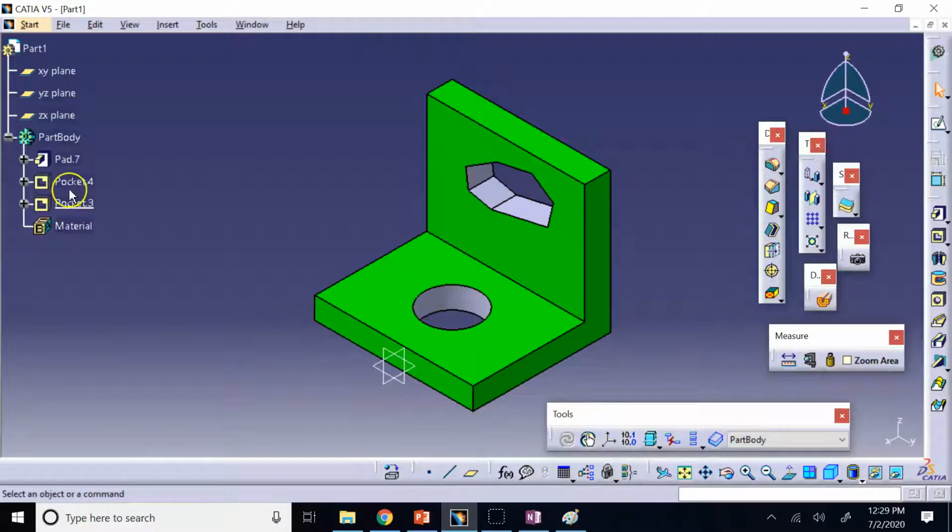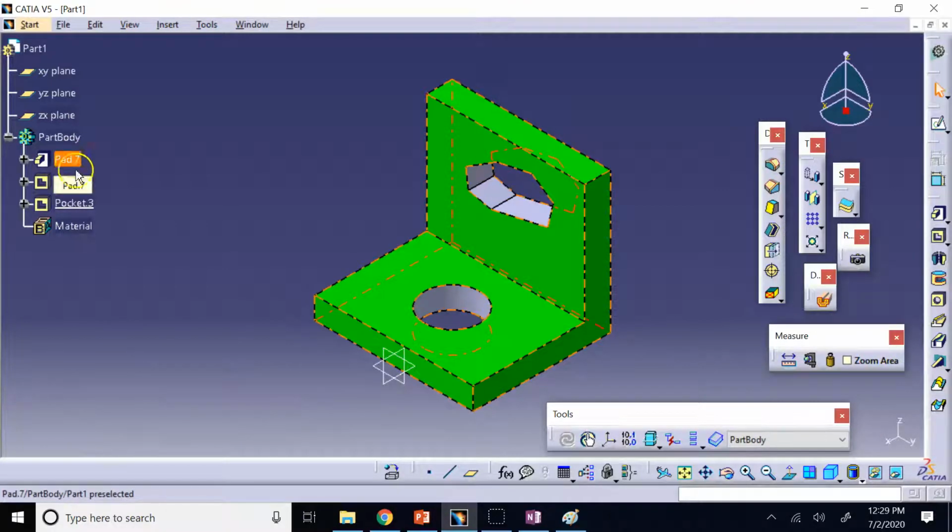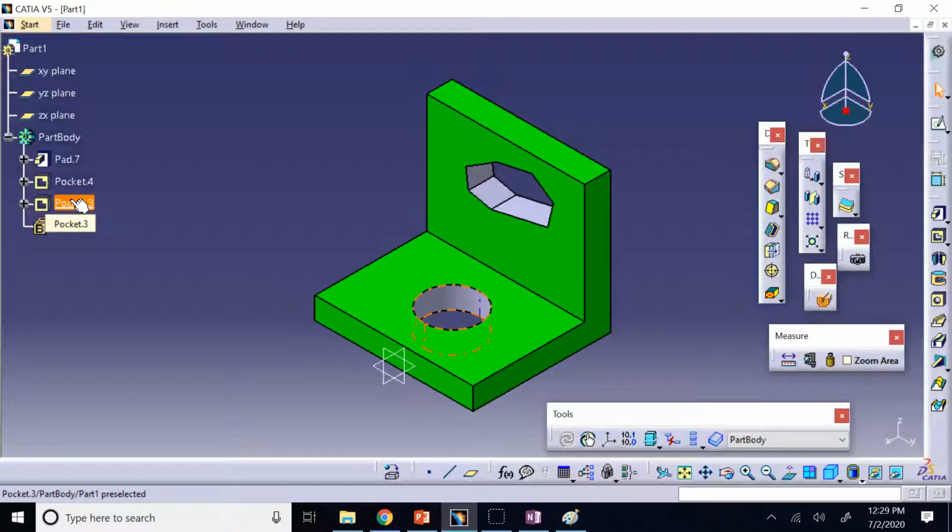So, in other words, in the definition of any feature, anything in CATIA, you cannot make use of features, sketches, or other things that you created afterwards. Each feature can only take advantage and benefit from the features and sketches created before it, not after it. Okay? Therefore, if you want that guide sketch to be used with this loft, and it was created later on, as I said, you cannot do it, but